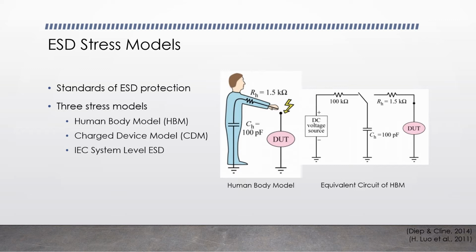Three major stress methods are widely used in the industry today to describe uniform methods for establishing ESD withstand threshold. They are Human Body Model (HBM), Charged Device Model (CDM), and IEC System Level ESD. IEC is the name of International Electrotechnical Commission.